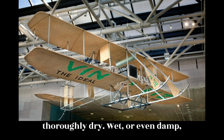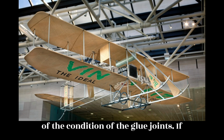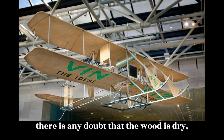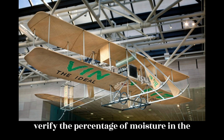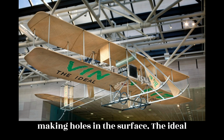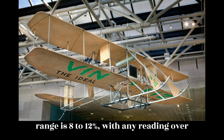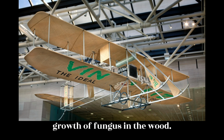Wet, or even damp, wood causes swelling and makes it difficult to make a proper determination of the condition of the glue joints. If there is any doubt that the wood is dry, a moisture meter should be utilized to verify the percentage of moisture in the structure. Non-destructive meters are available that check moisture without making holes in the surface. The ideal range is 8 to 12%, with any reading over 20% providing an environment for the growth of fungus in the wood.